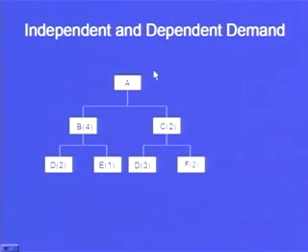On your screen, just to recall, we want to manufacture product A. Now, A requires part B and part C. The final product is A. Parts B and C will be joined together to make A. And how will we make B? B will require D and E. So, D and E will be assembled to make B, and then B and C will be assembled to finally make A. In brackets is the requirement shown for each part. So, 4 parts B will be joined with 2 parts of C to make A.